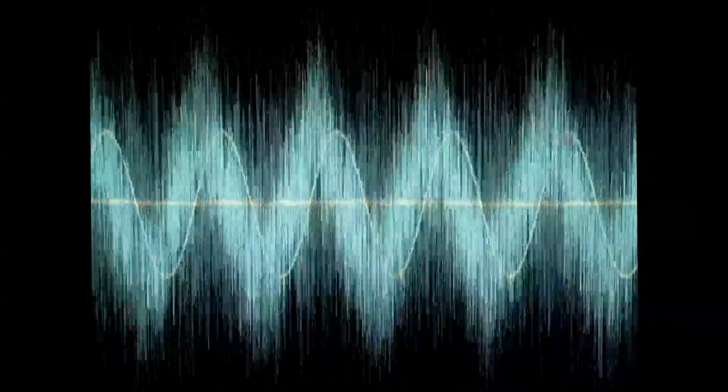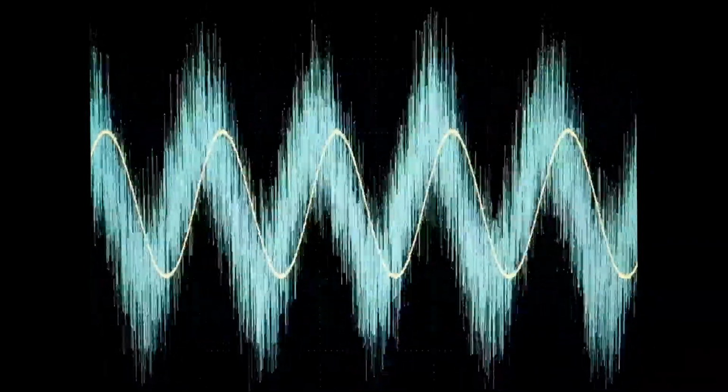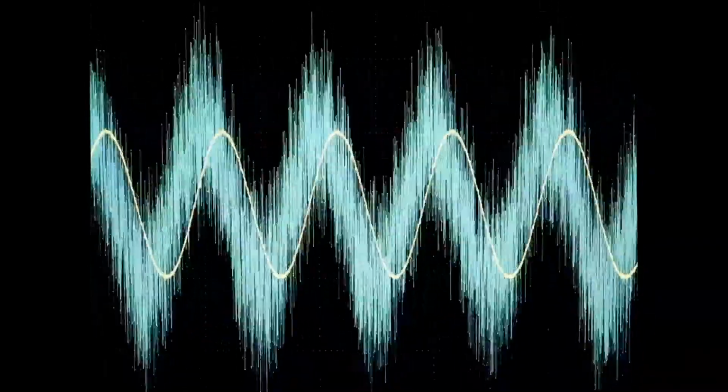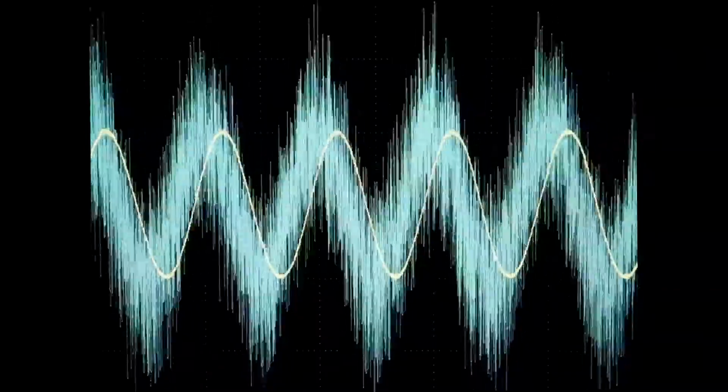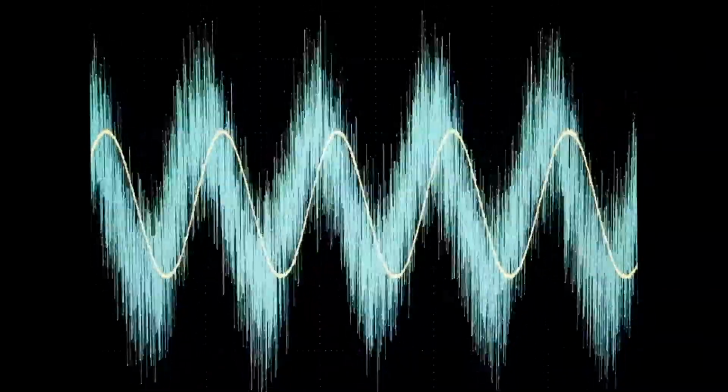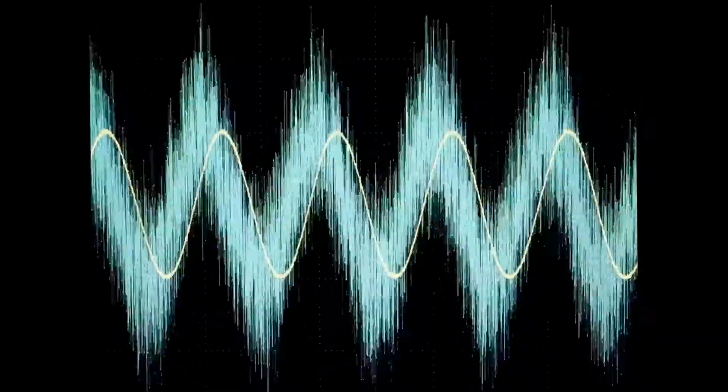Changing the input signal to plus or minus 10 volt white noise, observe that at the output, the noise is very nearly removed. Passing through are frequencies below the rejection band, causing a slight bit of wiggle in the output signal. Combine a fixed frequency tone with the white noise and look at the output. The pure tone has been extracted from the noise.